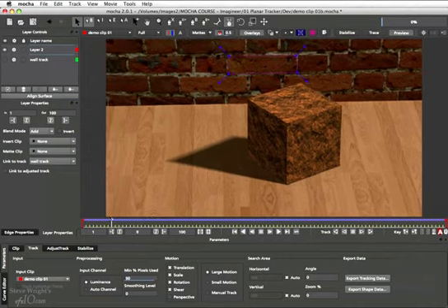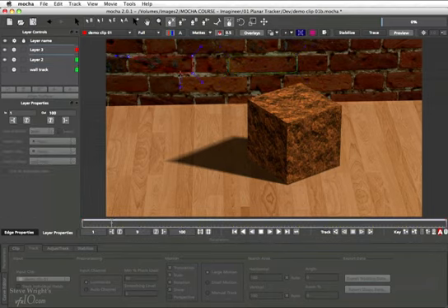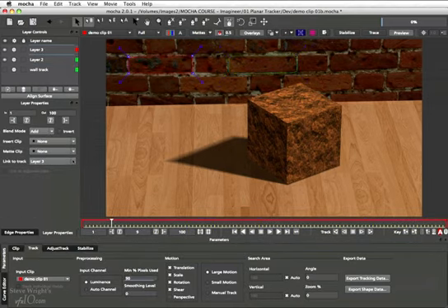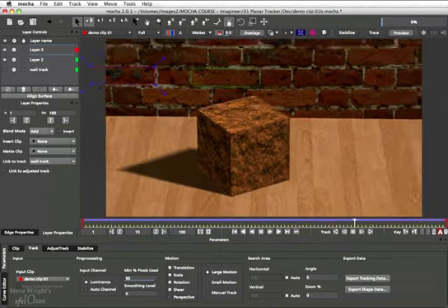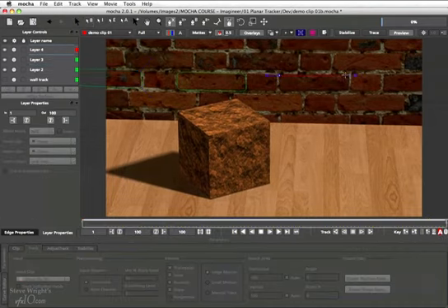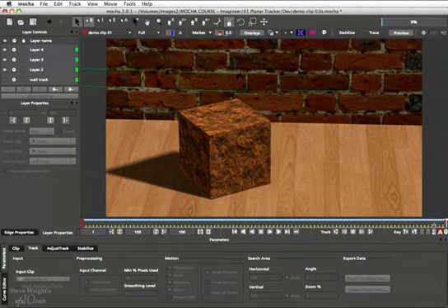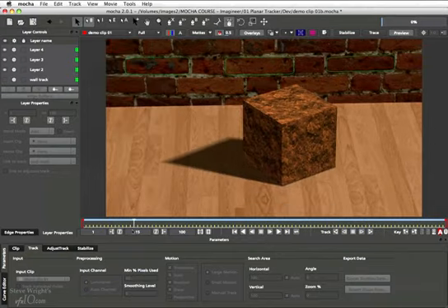Okay, I'll go to another frame. Here's another brick I'd like to mask. Draw a new layer spline, and link him to the wall track. And now he's attached to my planar tracker. And I'll move the playhead down here and go get another brick over here. And attach him to the wall track. Now all three of these rotosplines are tracking together.